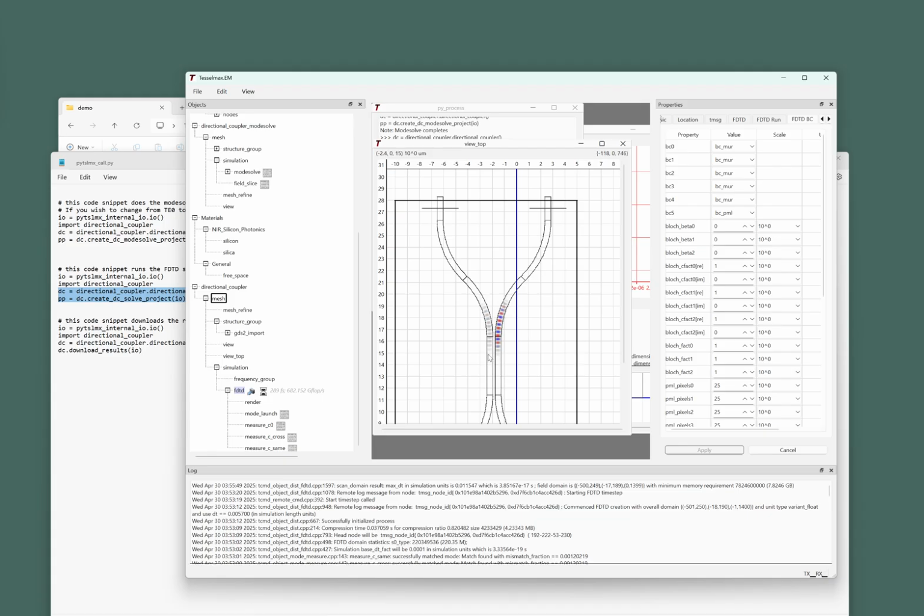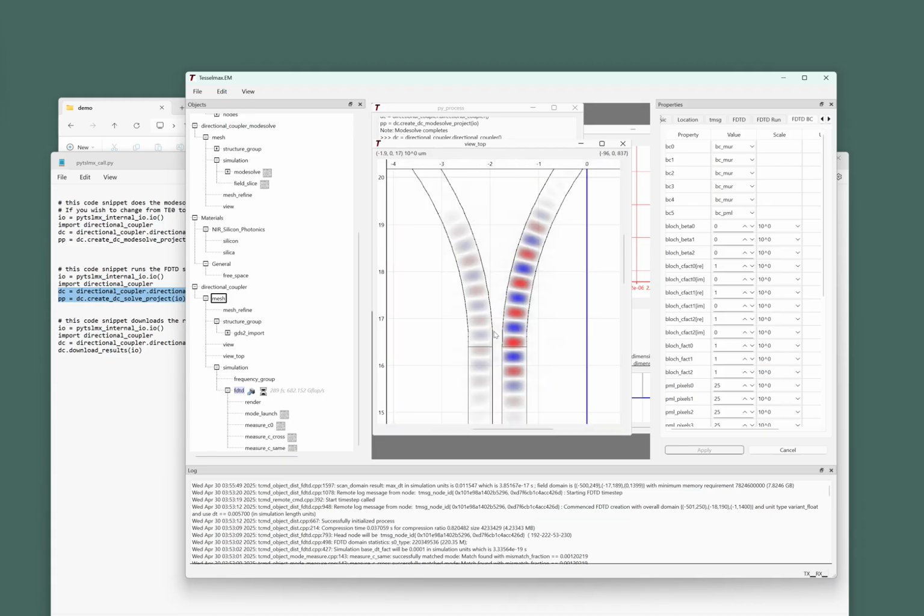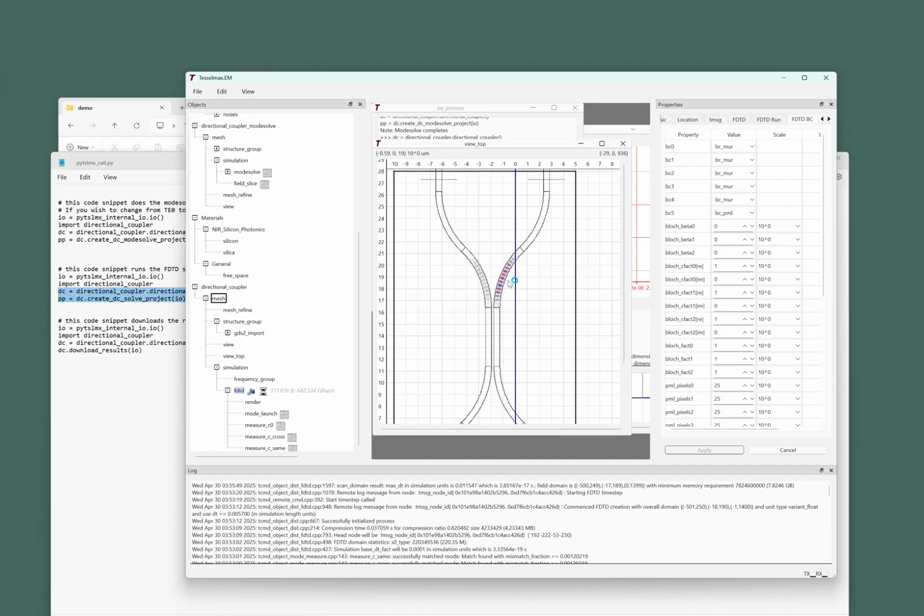Now, if you wanted to inspect the field here more carefully, you certainly could. What you would want to do is go to stop time step, not kill, go to stop time step. And that would simply stop the time stepping, but the fields would be available and you could interrogate them. I showed how to use the pointing surface and the field measurement surface in a previous video, but also you can simply go to a location with the field edit window and look at the actual field. I'll just do that now.